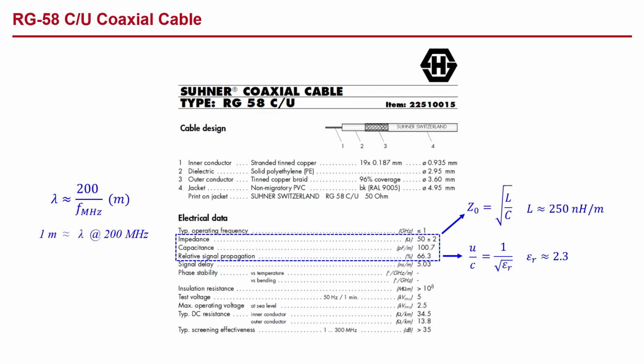Just as with our theoretical model, we can expect our resonances for a half wavelength to occur at about 100 MHz in multiples, for a quarter wavelength at about 50 MHz in odd multiples, and for an eighth of a wavelength at about 25 MHz in odd multiples.